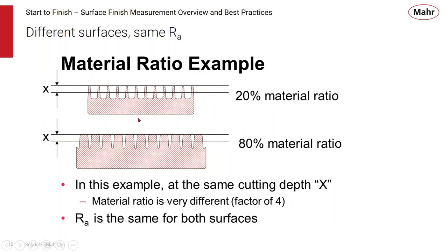So, you can see that if you had these spiked or peaked surfaces and that more rounded one, the bearing area on the peak surface is very small compared to the surface here. And by using a material ratio example, you can start cutting down on the surface, or say I want to take 20% off that surface, it can calculate for you how much bearing area is available, and you can do the same thing for this surface here with the more rounded area.